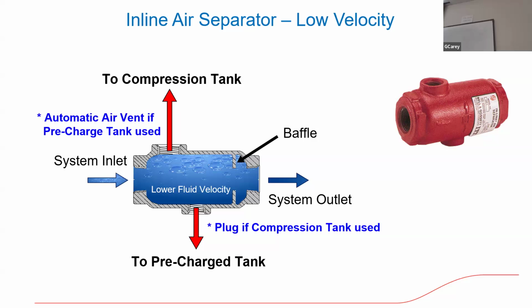And as we talked about before, when talking about system size and when you pick pipes, the sizing of the pipe, you're selecting 2 things. What's the frictional resistance? And then what's the velocity? Like on scale 2 and scale 3 on that old wheel we talked about. So typically system flow is around 4-5 feet per second. And that's good. That's all good engineering principles.